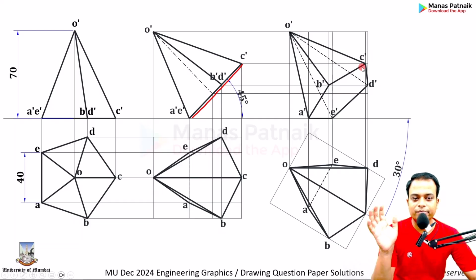So a little bit of imagination is very essential on your part to make sure that you are drawing it correctly. These two triangular faces are clearly visible, and behind these two triangular faces are these edges, OD and OE. Since they will not be visible directly as they fall behind a face, they have to be represented with dashed lines, being a hidden feature.